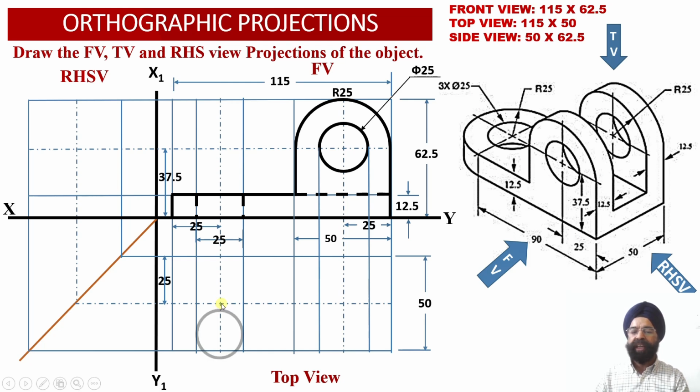So having located the axis corresponding to the circular hole which is lying into the horizontal web which is lying onto the base of the solid as element number 1 over here, now we have been able to obtain the location of the circular hole having diameter equal to 25 millimeter. We haven't marked the diameter over here because we already know that there are going to be 3 holes and all of these holes are going to measure 25 millimeter each.